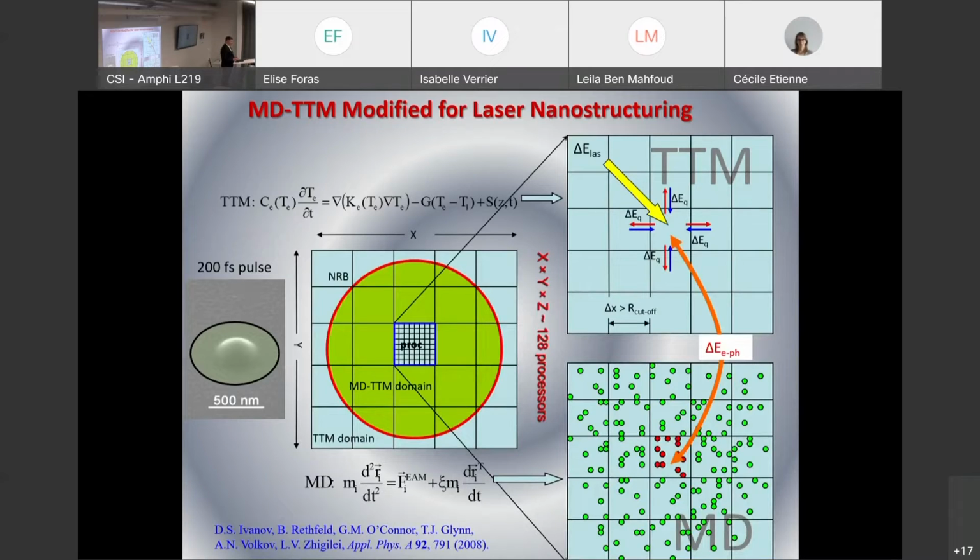So we divide our region, this is the top view, into a number of cells. Each cell will be governed by a single processor, its own processor. Each processor volume is divided into a mesh, a two-dimensional mesh, inside of which we solve simultaneously the combined continuum-atomistic method. So we solve in the three-dimensional case the diffusion process, laser light absorption, and non-equilibrium directly accounted for in coupling with the molecular dynamics representation.